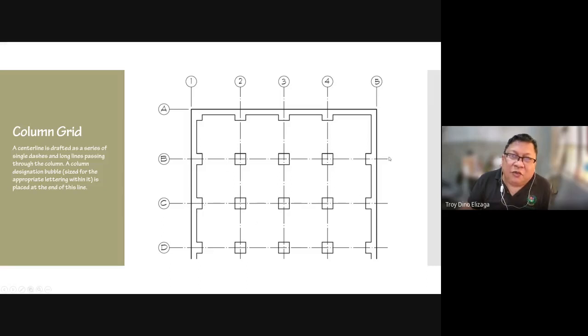the construction drawing. So when you draw your floor plan, put this first, the columns, the walls, and then the grids before any other details. Because chances are, if you forget to put this and put this last, you might be drawing over some text and numbers along it. Okay, and you can't avoid it anymore.